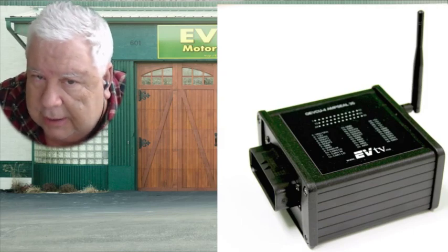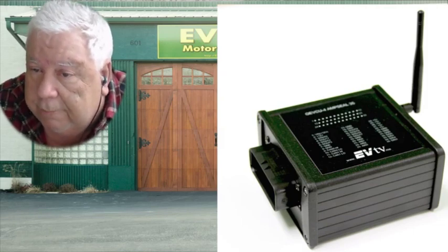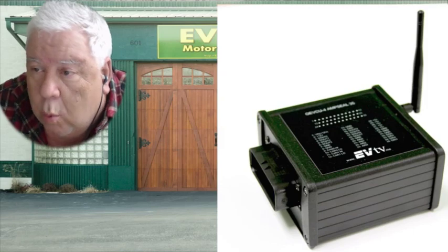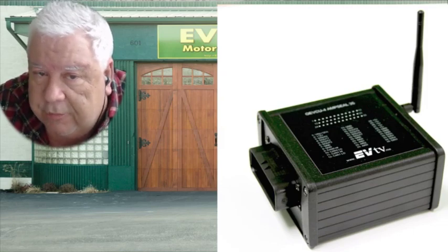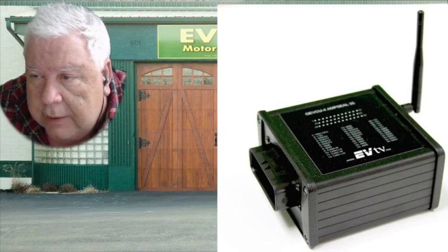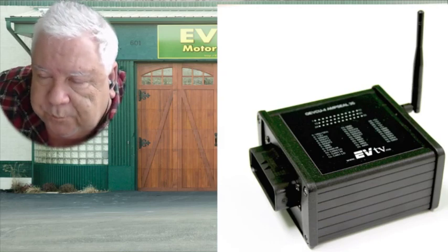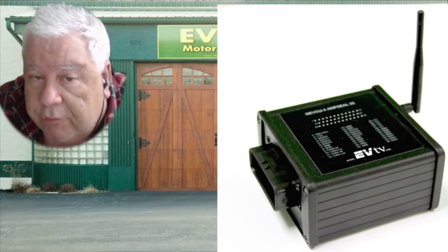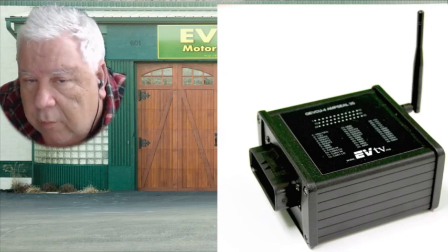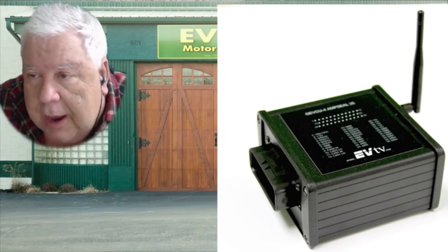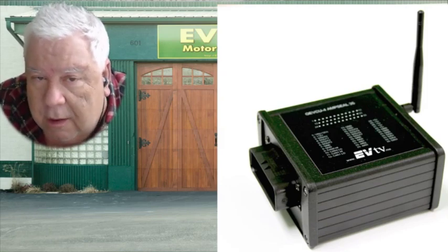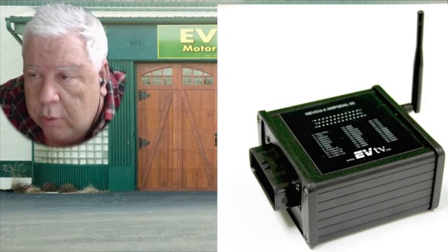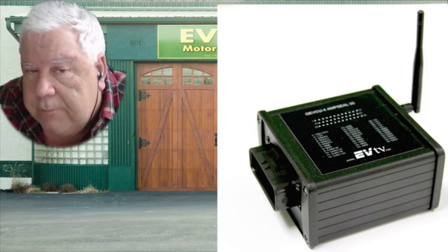A little bit further complicated, there are actually two processors in the JEVCU. In order to have that wireless web page interface and not interfere with or take away from our main controller operation, which is to drive the inverter, there's a second processor in the box. A Connect One module handles all the wireless and all the web, and holds an image of a website that we actually upload wirelessly to that module.